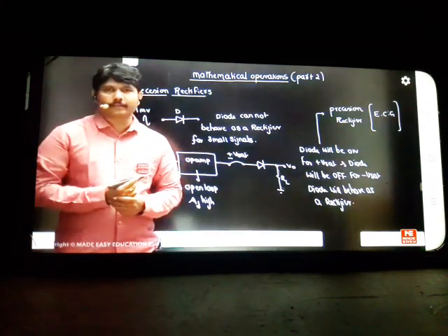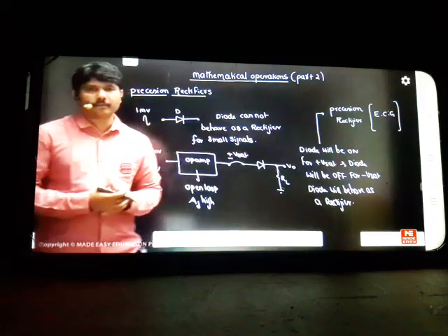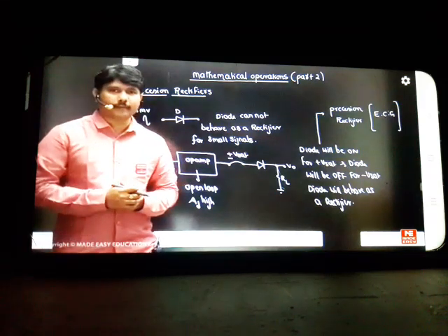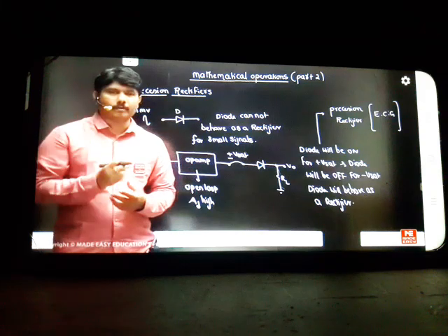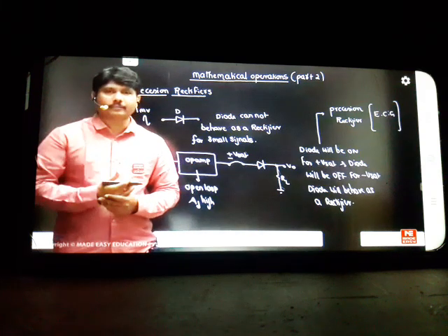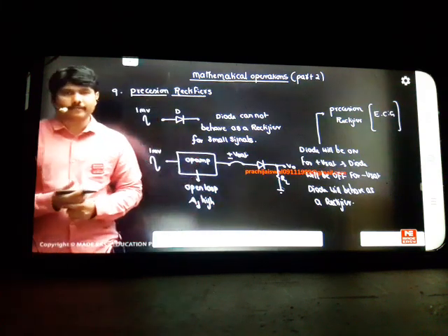In previous years, we had a separate instrument for that. Now in the watch itself, we can check the heartbeat rate at every instant of time. That is the beauty we have. So ECG we call electrocardiograms. In that, whatever heartbeat rate you are getting comes as small signals. That has to be rectified and converted into a DC value. Then this type of instrument uses what are called precision rectifier techniques.